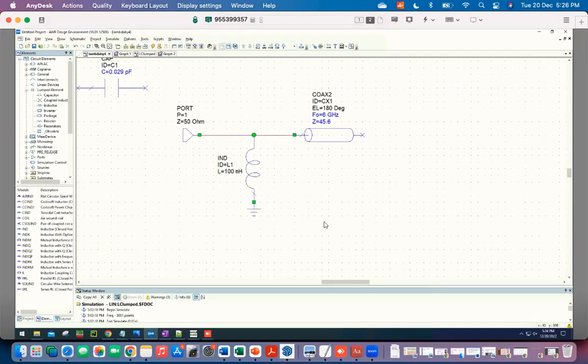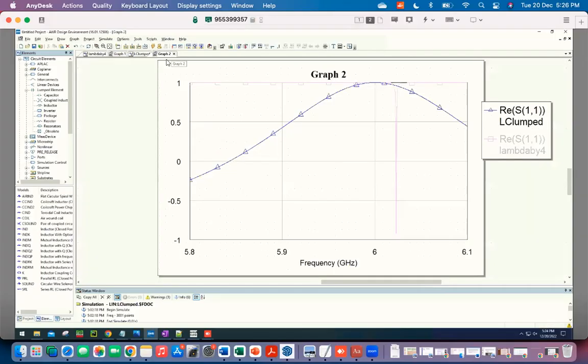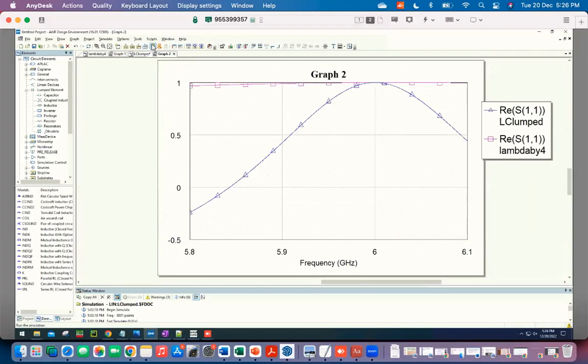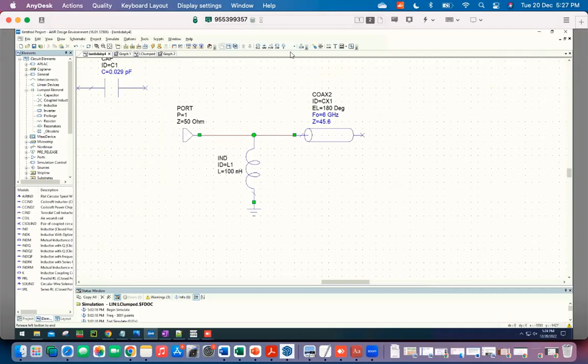This might appear strange, but essentially it's doing the same thing. It's creating an impedance mismatch point here. So the waves which appear here, they will see some impedance which is not 50 ohms. Right? So that will cause a reflection. But now you don't want this inductance to be too big either. So you have to see whether that actually works out for this. Because basically a very large inductor means it's almost not there. It's connected directly.